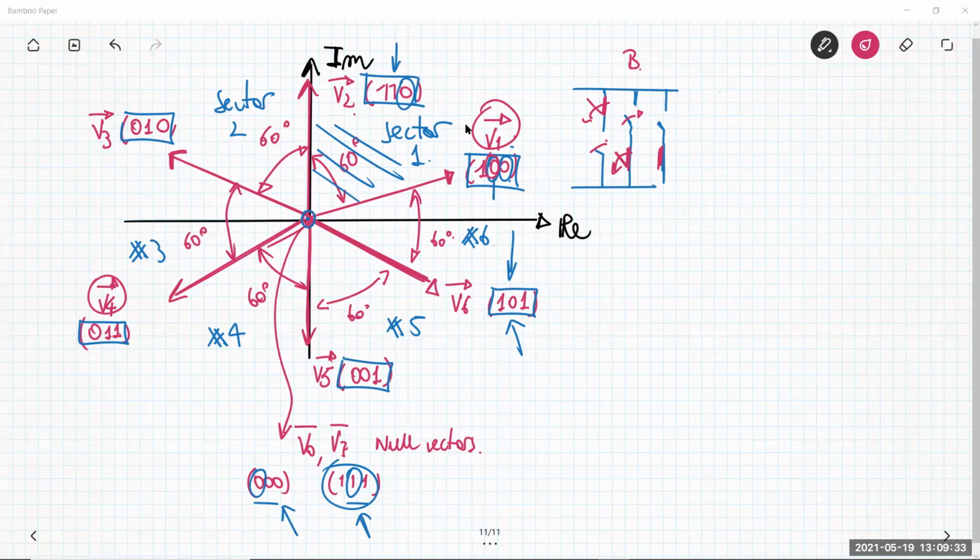Let me just answer the question. Marco Simonetti asked, the combination is similar to half stepping. Half stepping means the stepper motor. You are talking about the stepper motor. Half stepping is the combination in which you excite one phase and then two phases, then one phase. You alternate the one and two phases. You are referring to that specific operation. Is it similar to that? I don't see any similarities here.